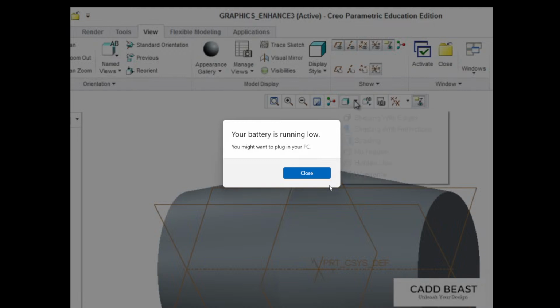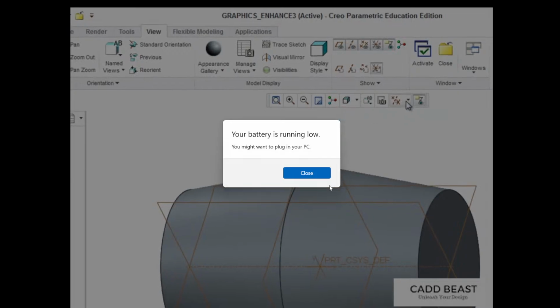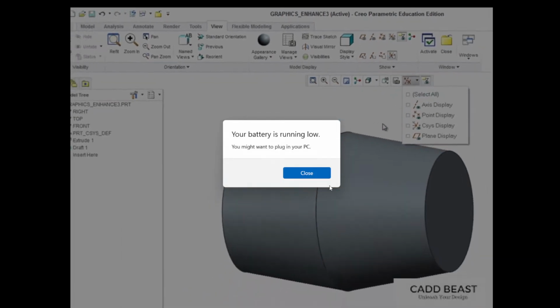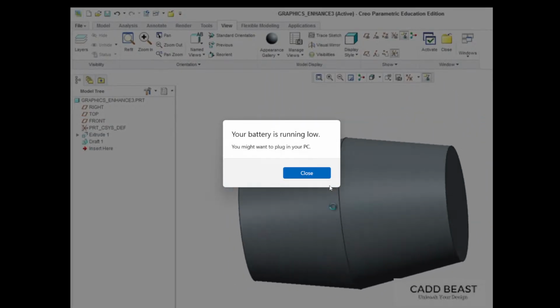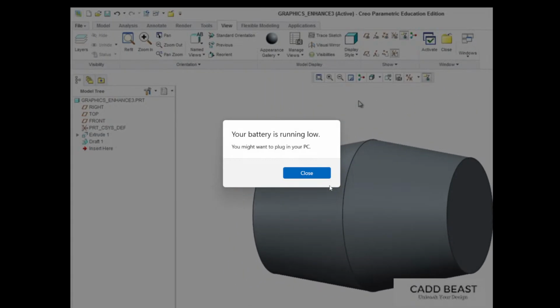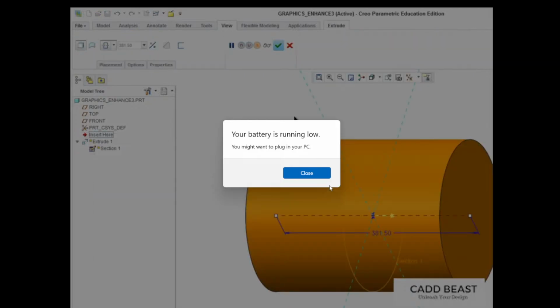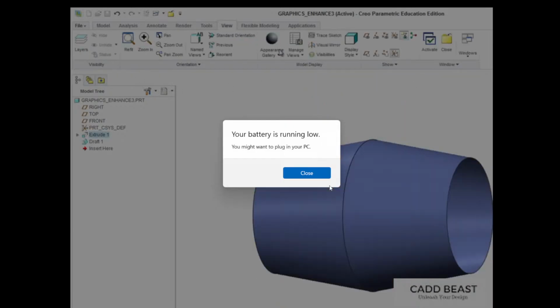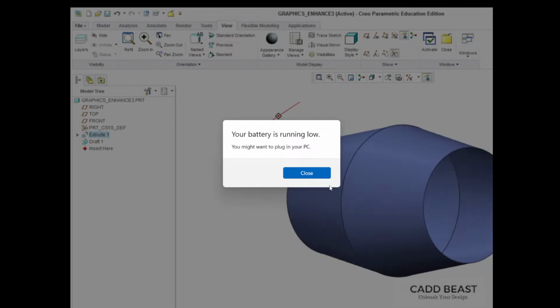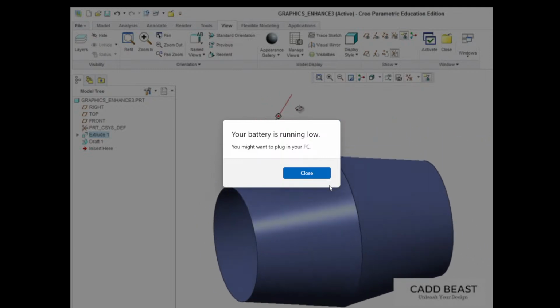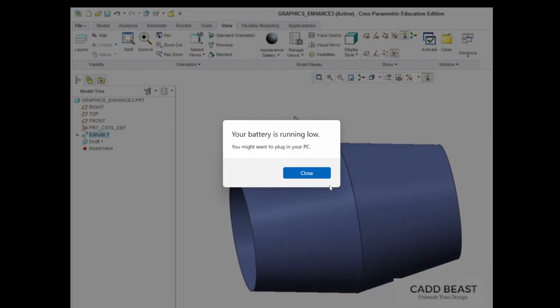Creo Parametric includes a new model display type called Shade with Edges. When this display is activated from the Graphics toolbar, all model edges are displayed in black, making the details of your model easier to see and work with. If a solid extrusion is edited to be a surface feature, you'll see that it changes from the gray to a blue-violet color that contains higher shine and reflection. This is true for all surface features in Creo Parametric.